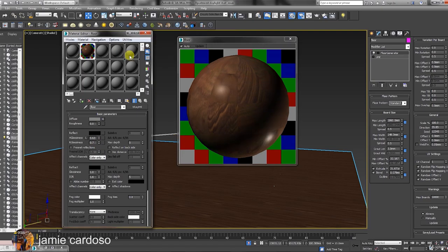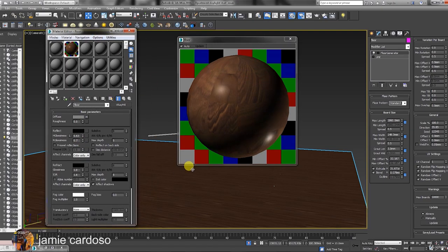In the real world, most surfaces reflect light unevenly. To replicate this effect in 3ds Max, we're going to first select and drag the contents from the diffuse toggle into the reflect toggle. Choose the option to copy and OK to close the dialog. A copy of the multi-texture procedural map is now inside the reflect toggle. Reflection and glossiness work best with black and white and grayscale materials.